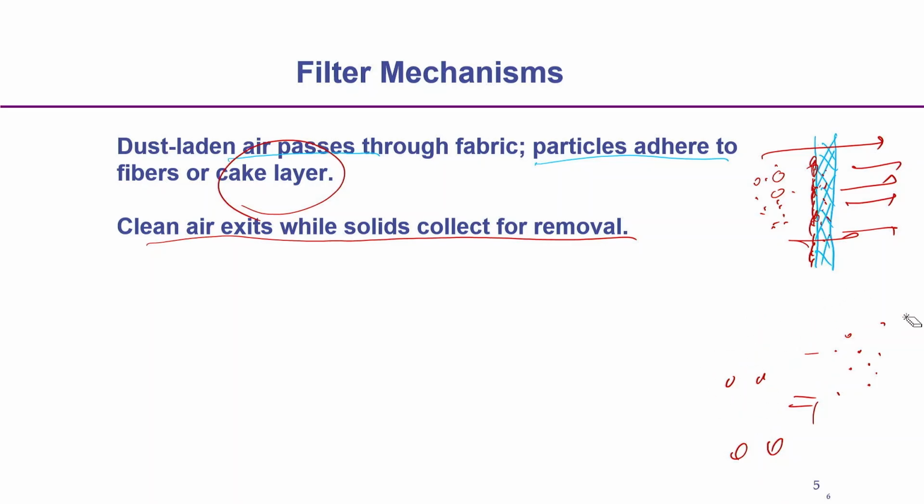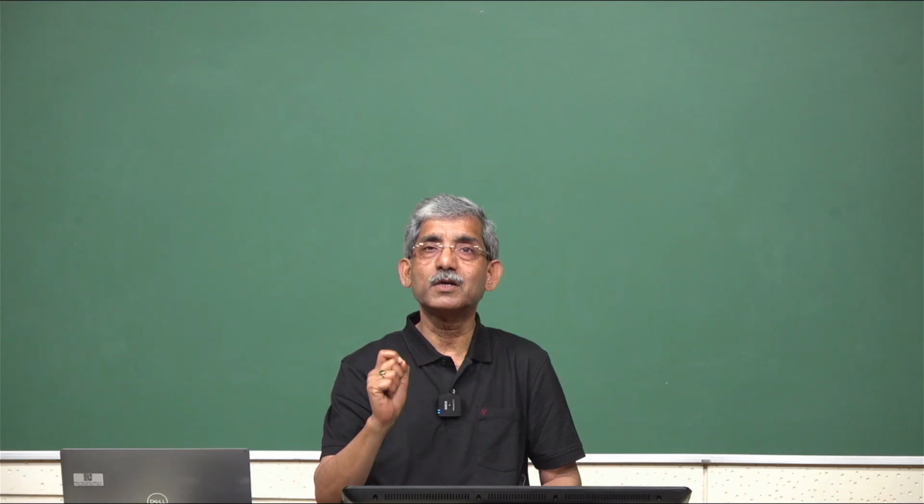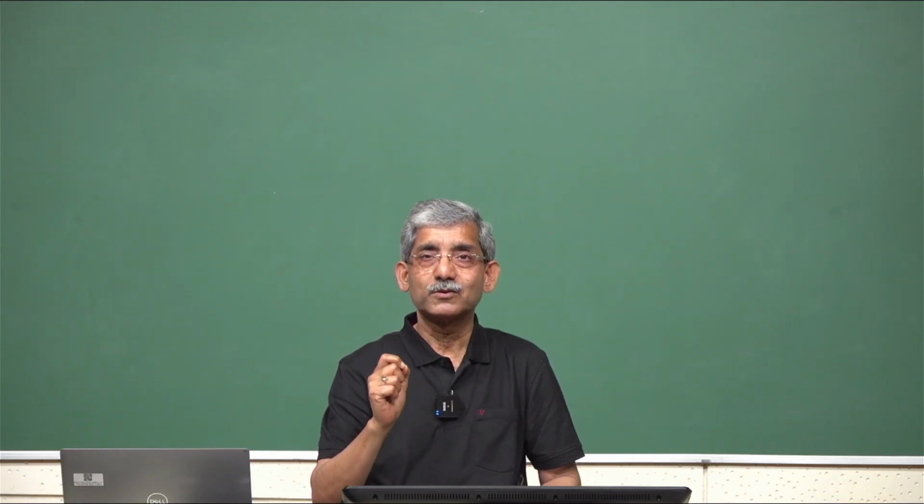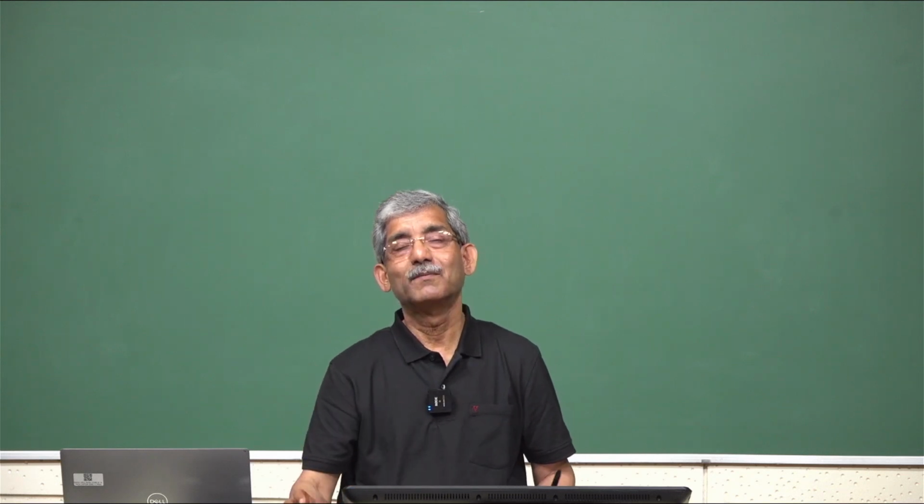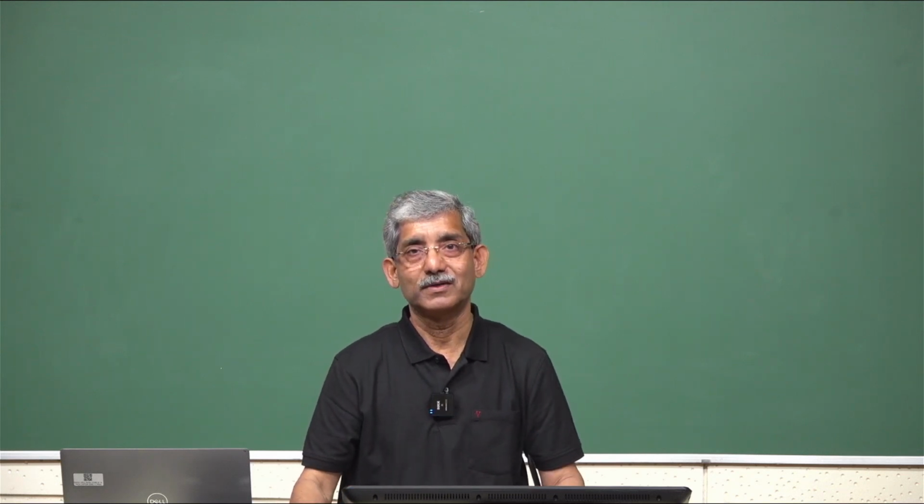In filtration we cannot allow the smaller particles even. Ideally all the particles are to be restricted, but not by reducing the pore size. We cannot reduce the pore size too much, because it will increase the pressure drop, that we cannot have.